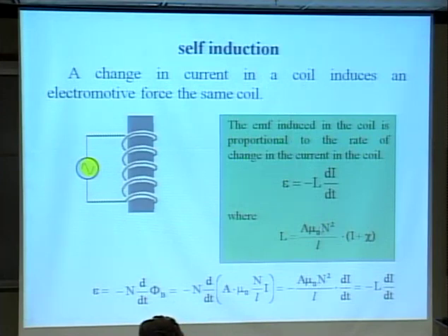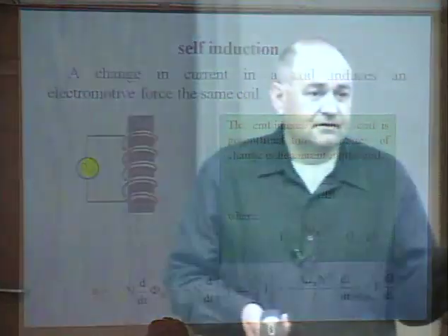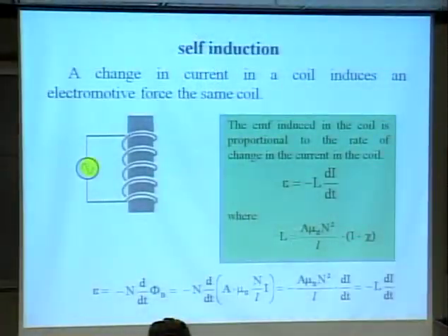Why would you do that? In what circuit would it be important to adjust inductance to the appropriate value? In a resonant circuit, you have to tune that radio or TV to appropriate stations. The combination of capacitance of the capacitor and inductance of the inductor determines what frequency you are going to receive.